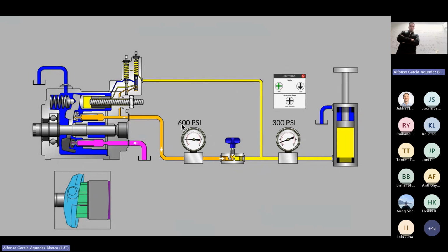So in this particular case, we've got a pump that sets its outlet pressure just slightly higher than what's needed by the load. We've got to have some kind of a flow controlling device in there. This is our needle valve that's being used to set our desired cylinder stroke speed. But let's have a look at what happens when I add a brick to the brick stacker.